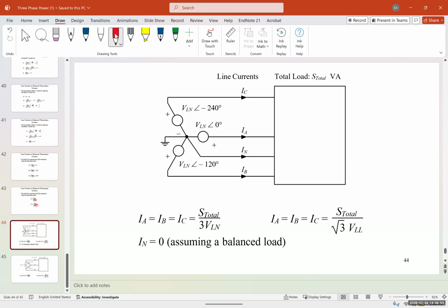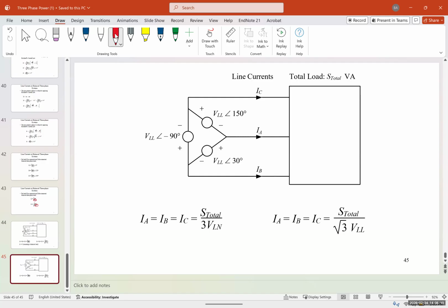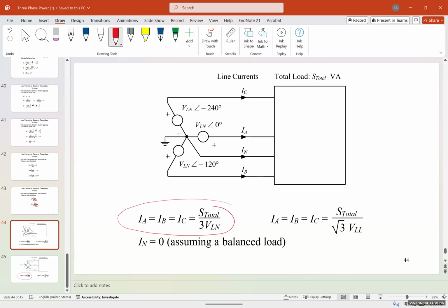But for now, just know that motors start on three-phase on the star connection, and then after like a fraction of a second or 1 second, they go to delta. The reason is because of torque and the power consumption, and I'll explain more about that later on. Just for now, you need to know that the power in a three-phase Y connection is as follows.